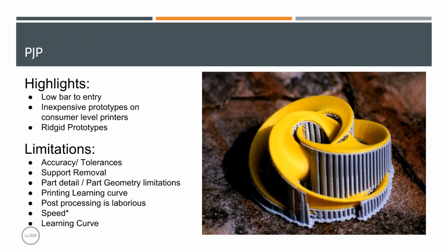Also, there's a significant amount of warpage that happens on these parts when you do print out large cross-sectional areas. They do tend to delaminate from the build plates, and again, I'm sounding like a bad salesman, but I'd rather you guys get the entire gist of the products via a webinar as opposed to after you already made the investment, right? So there's limitations to this technology in general.